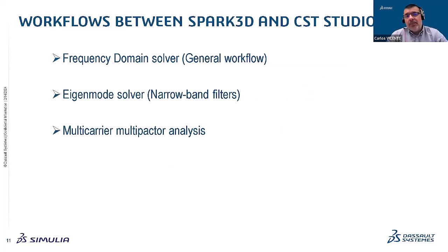Now, there are several workflows between SPARK3D and CST Studio Suite. I just want to go today through 3 of them. Basically the general one, which is the most commonly used. One interesting workflow related to narrowband filters, thanks to the eigenmode solver. And finally, the multi-carrier, multipactor analysis, which we have improved recently thanks to the incorporation of the European standard in the calculation. I will go through that.